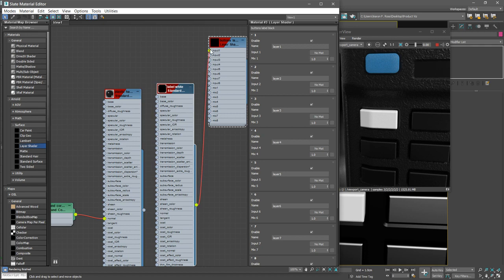And you might wonder why, because you might think that the label would be on top of the plastic, but it's because the map that I'm going to use has a white background and black lettering, and black is transparent, whereas white is opaque. So we actually want to reverse the front and back relationship here because the image that I'm using is actually reversed or inverted. Okay, so we also want to connect the plastic hard black to input 2. That's going to be on top or in front.